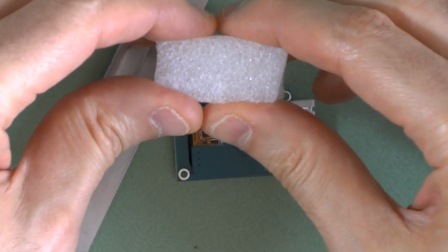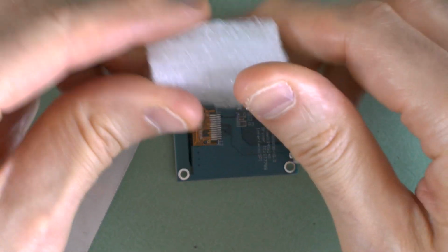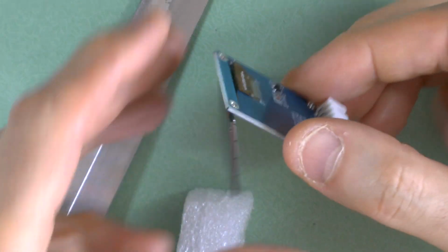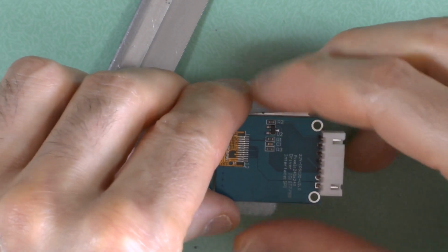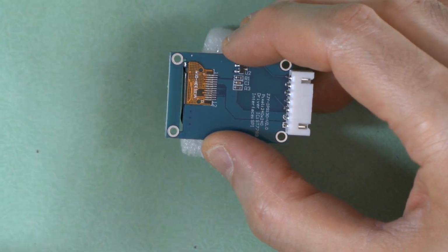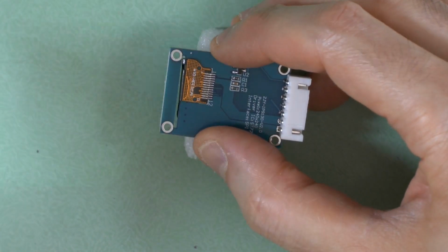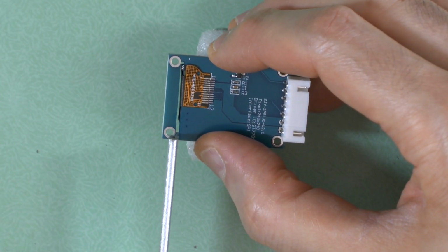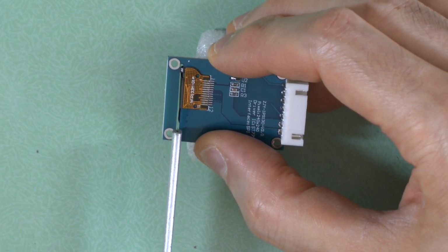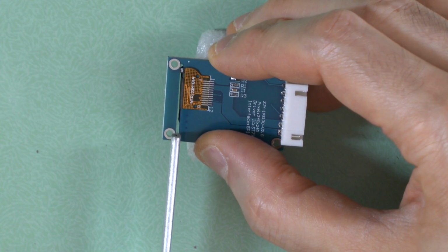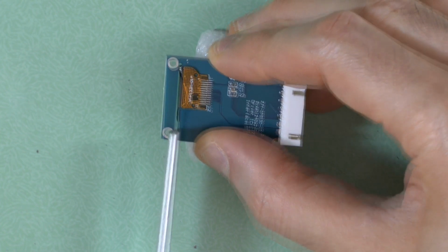Carefully, gently and slowly use a fine-toothed craft saw to make score marks on the PCB on the two sides of the slot that the TFT screen ribbon cable passes through. The side that has the greatest clearance from the ribbon cable is scored horizontally until all the copper layer on both sides has been cut through, and some of the PCB substrate material as well.